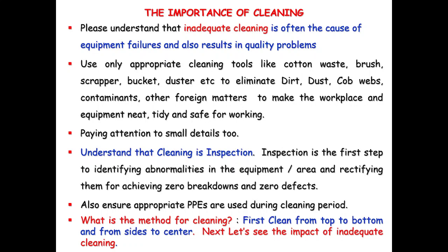Paying careful attention to small details is very important during cleaning. Understand that cleaning is inspection. Inspection is the first step to identify abnormalities in the equipment and area and rectifying them for achieving zero breakdowns and zero defects. Now let's see what is the method for cleaning. First, clean from top to bottom and from sides to center. Everyone should be taught about the impacts of inadequate cleaning also.